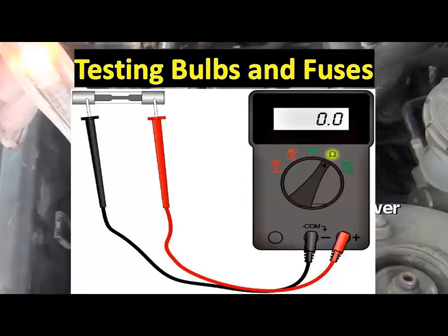Some moisture formation in non-vented composite headlights is normal. The glass envelope on halogen light bulbs should not be touched with your hands or fingers. Many light sockets are removed by rotating them 45 degrees counterclockwise. That's a standard design of the bulb. The bulb should be removed 45 degrees counterclockwise and then put back clockwise. Most of the bulbs have two indexing pins between two sides.